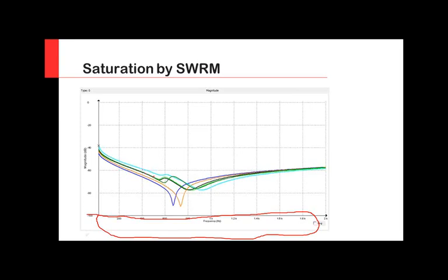What's happening now? First of all, if you look at the original signature that we had, the symmetrical phases, now the response is not symmetrical between those two. So that is the first clue. You're testing phase A, you're testing phase C, and now those two don't look symmetrical. The other one, you will clearly see that there is an impedance deviation here, and you will see also that the first resonance on the non-symmetrical phase has a frequency shift, right?